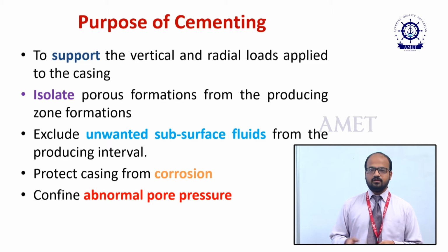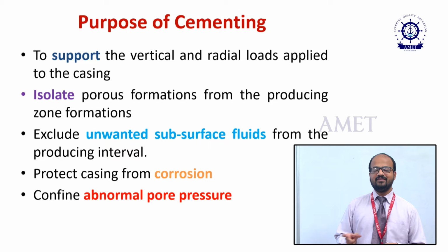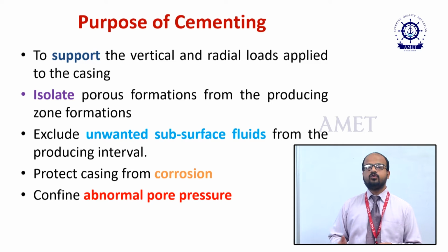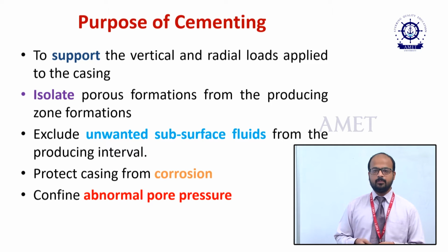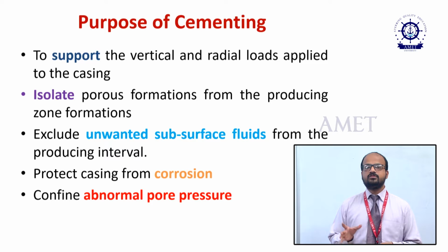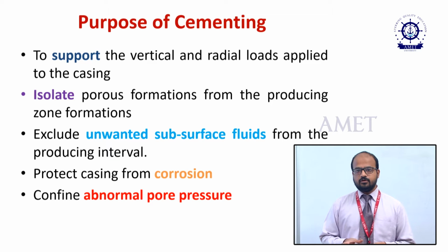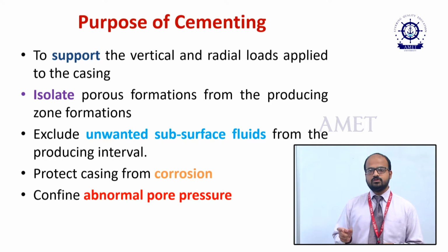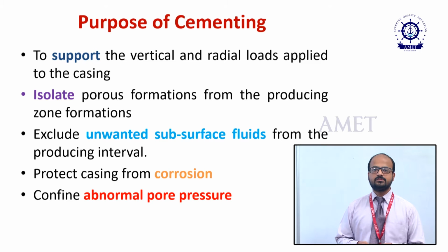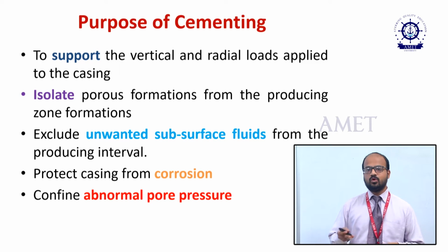If it is only the BOP stack, the weight is like that, and then we have to put other equipment from the rig, which should also be withstood. If the gap exists in the annular space, then what happens? Again it will start to shake and your wellbore may lead to collapse.